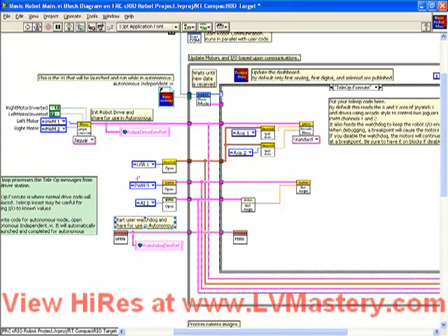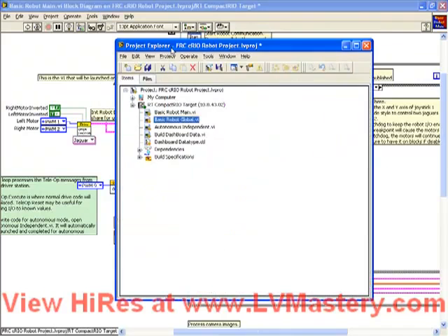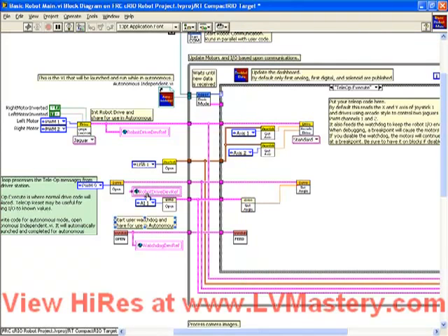What we need to do now, I'm going to just move this guy over to make a little bit more room. What we need to do now is bring up a copy of that global. We can do that just like we've been making copies of things for a while now by using the Control key and dragging an existing global. Another way we can do it is if we go to the project window, we can actually drag the global from the project window onto the block diagram. And then all we need to do is access the finger tool by clicking in the center to choose the right reference. And in this case we want our pan servo reference. And remember, we want to write to it.